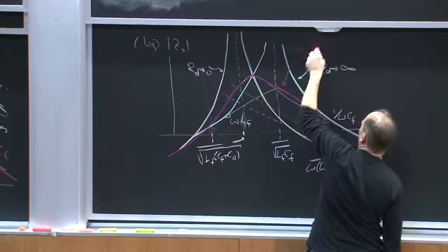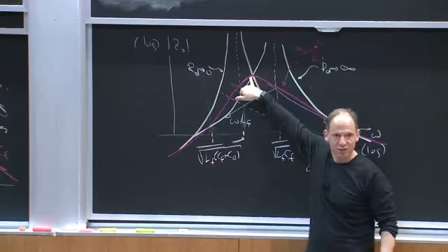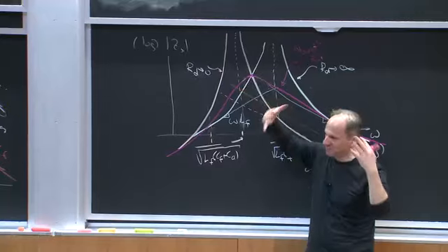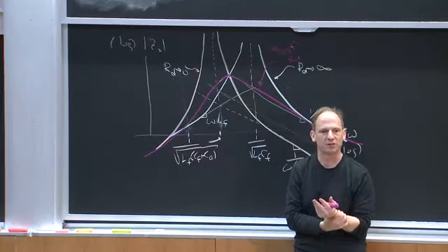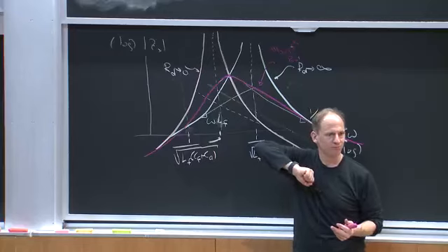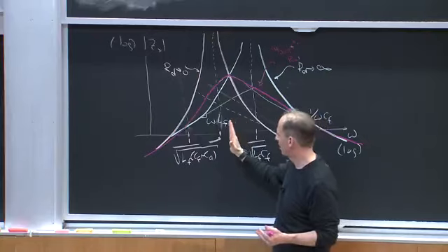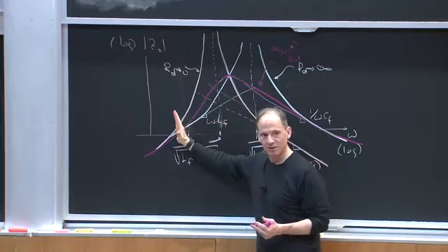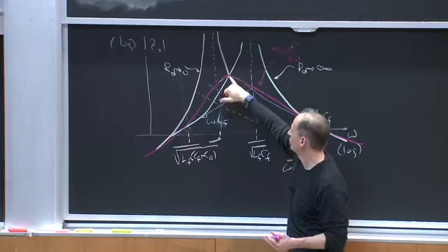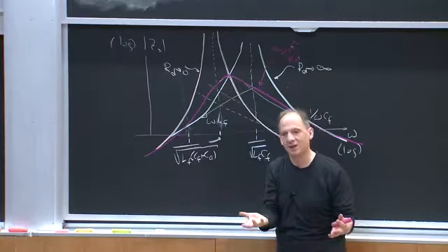That's a pretty crummy drawing, but this is the best RD, in terms of limiting how big the output impedance gets, which we could take as some kind of measure for how badly damped the filter is. Questions about that? So what do I do if I don't like that value of output resistance that I get? Well, if I make CD bigger, I can slide this down, and then I'll pick a different value, which will bring this intersection point down, and we'll get better damping.